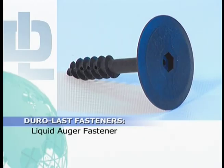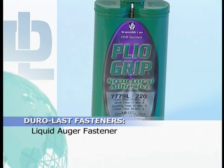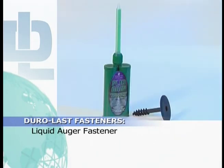This fastener has a hollow shaft through which a 2-part epoxy may be injected using a dual cartridge caulk gun. The liquid flows down through the shank and out the disbursement outlets into the surrounding substrate, where it then hardens. For full information, refer to the product data sheet in the Duro-Last specification manual.